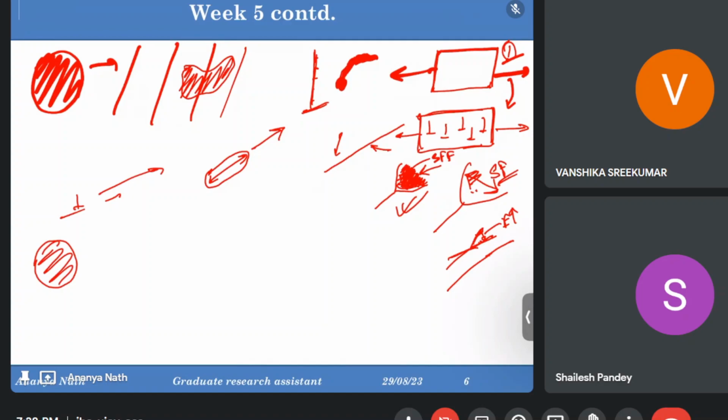So annealing is like we heat up the material up to a certain temperature for a certain time. In most of the cases, it's more than the recrystallization temperature, and then we cool it down in the furnace itself. So you can imagine for stainless steel, mild steel or aluminium also, we sometimes do the annealing at 950 degrees centigrade, and then we let the material cool down inside the furnace.